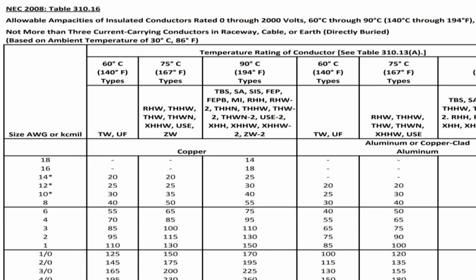Say you got a huge, big, wide diameter pipe, okay? You open it up, but it doesn't have much pressure, it can still fill something quick because there's so much coming out at once. It's the same thing we're dealing with here. The higher the voltage, the higher the pressure, the smaller pipe we need to do the same thing. Now let's pop over to the NEC ampacity table and take a look at what this variance means.